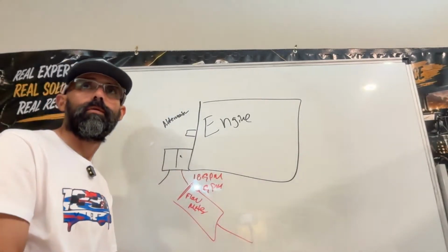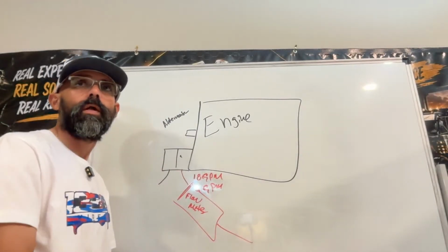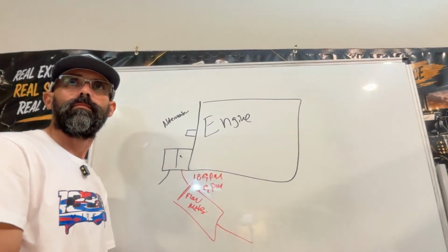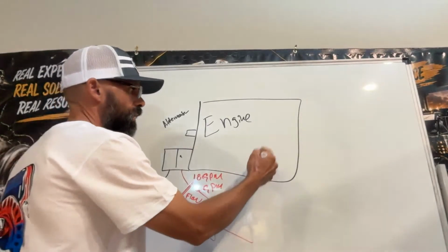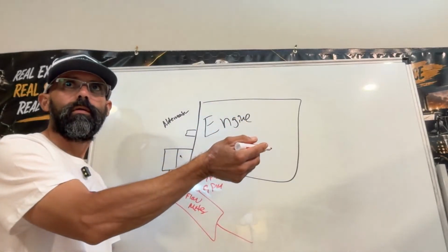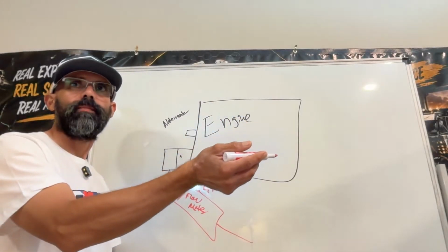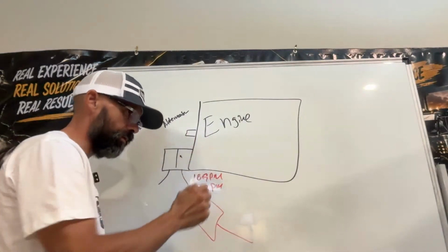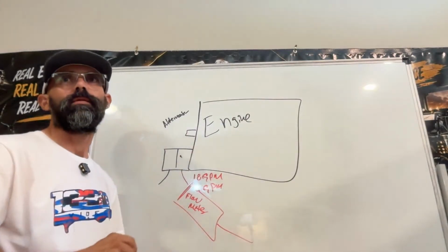then you have an issue in the pump. Probably worn out. Simple. That's why you're not getting your charge pressure that you're supposed to get after you went through all the process. You need to have a flow meter so you can read GPMs.